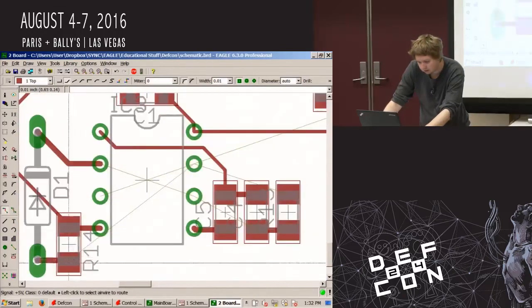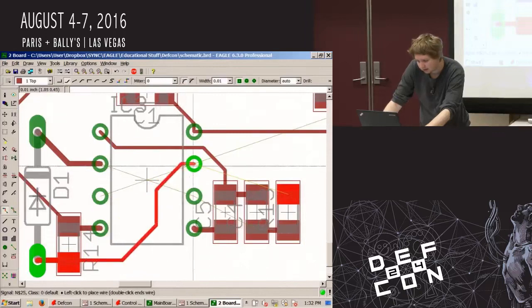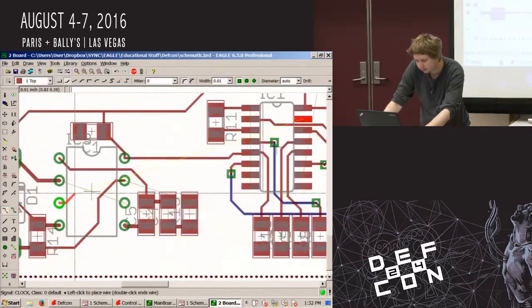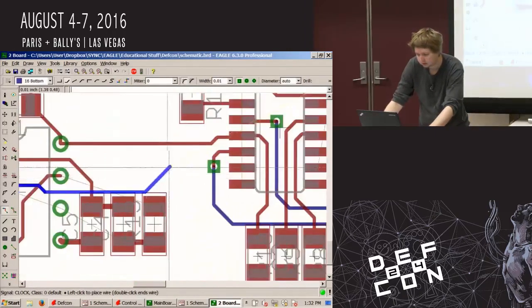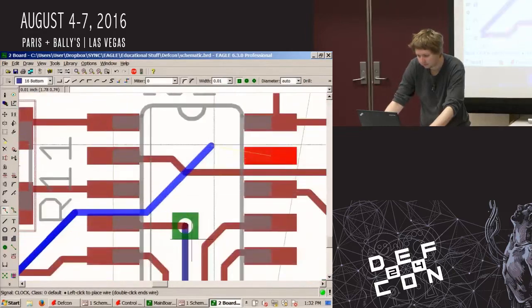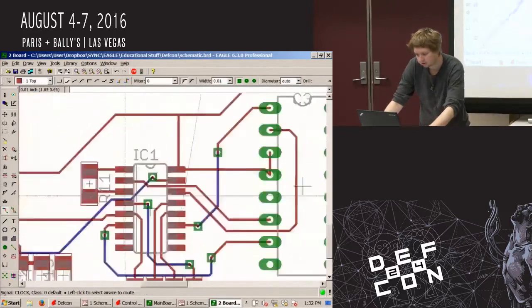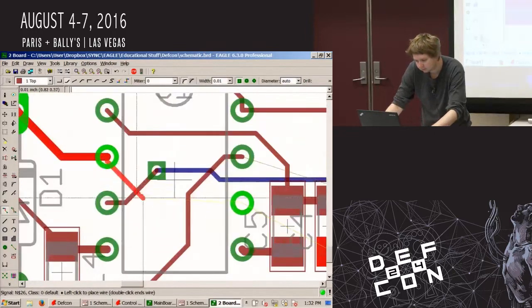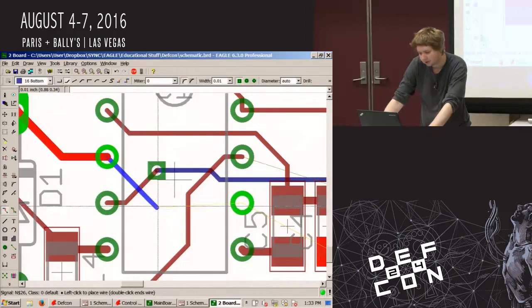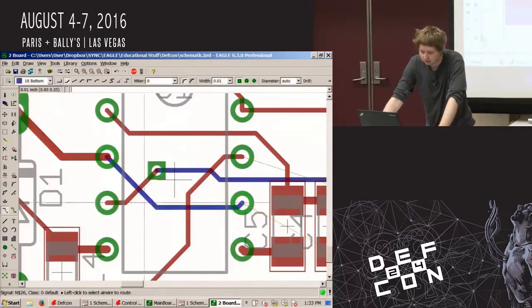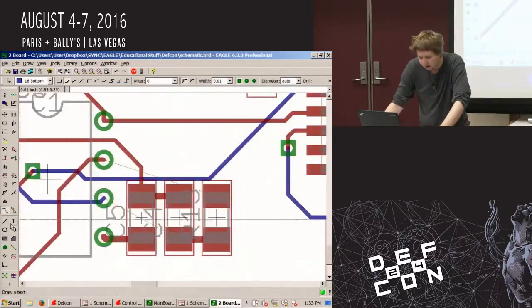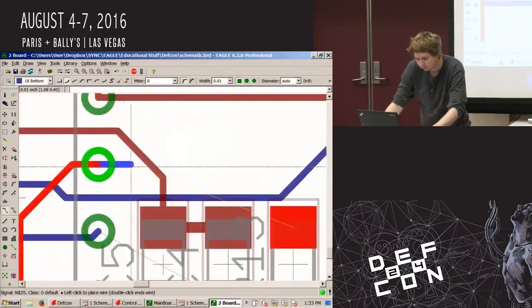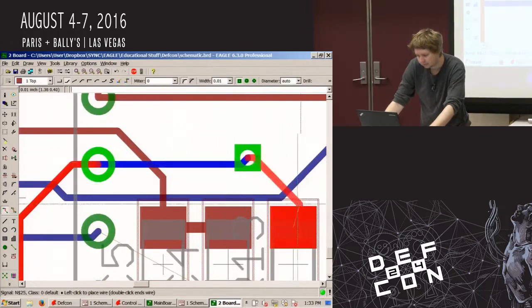Alright, so power, whatever that thing does. I think this might actually be my clock. So go down there. In this case, I don't need a via. I can just go straight down. And then right here, I really didn't need a via either, but then I'd have to have a via somewhere just so I don't have my traces touching. So via up here.